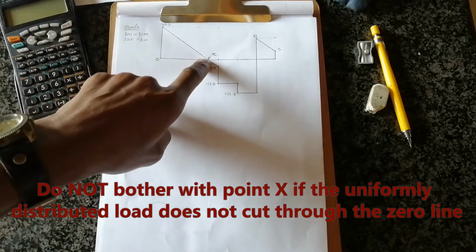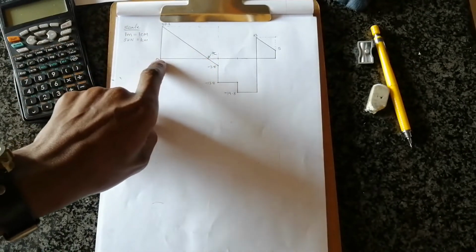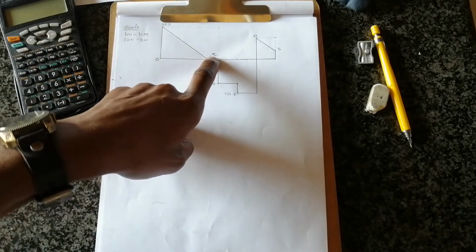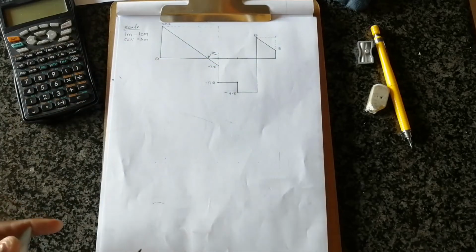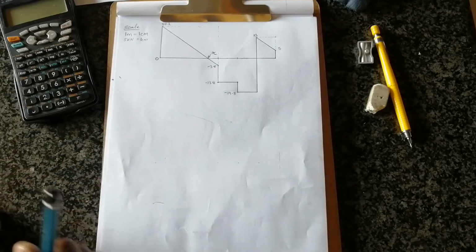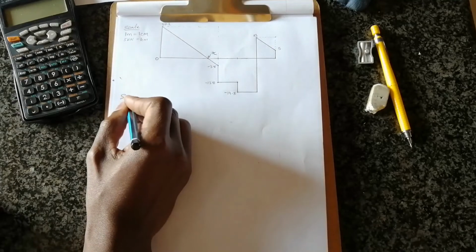Do not worry about point X if it does not cut through the zero line. You only worry about point X if your uniformly distributed load goes through our zero line, and that is where we get to do some extra work. But without our uniformly distributed load cutting through the zero line, there is no need to calculate for that distance X and so on. All right, so the first thing when we are drawing, we state our scale.